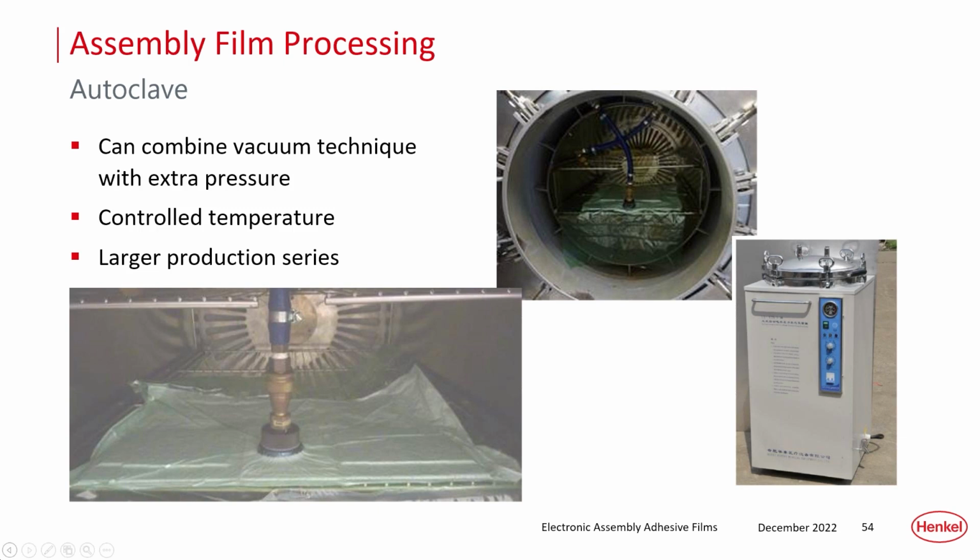Another way is to use a vacuum bag: build the parts up, put them into a vacuum bag and pull a vacuum, so you can get up to one atmosphere pressure. It's not very high, but it's very uniformly applied and cures within the vacuum bag. Or on the next one, if you really want to over-engineer it, you could put that vacuum bag into an autoclave and increase the isostatic pressure on the parts during cure. You're beginning to look at capital investment here with autoclaves and whatever, but some companies have this type of thing.